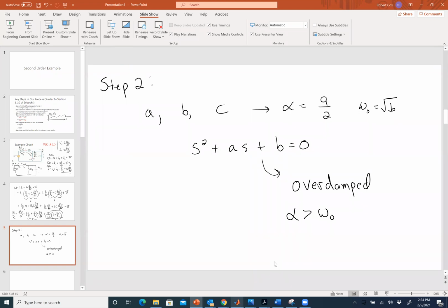So what does that mean if I have overdamped? The roots of this characteristic equation, how do they appear? What's the defining characteristic of overdamped in terms of those roots? S equal to negative alpha. Well, give me more succinct. What can we say about them? Are they real? Are they complex? You got two choices. They're purely real. This is the case where they're real and distinct. And what do I mean by distinct? Unique. They're different. They're two different values.